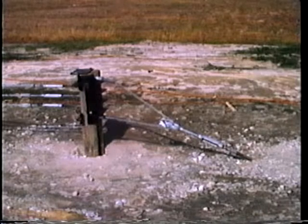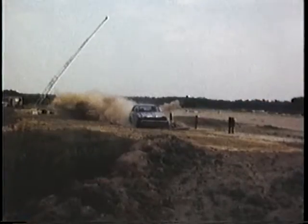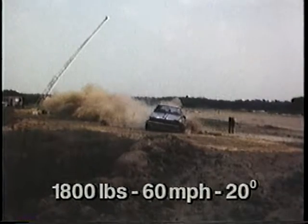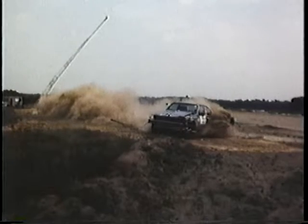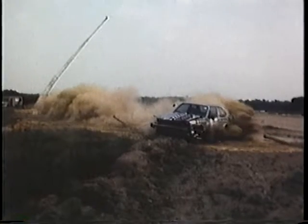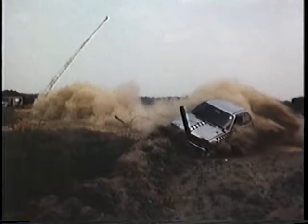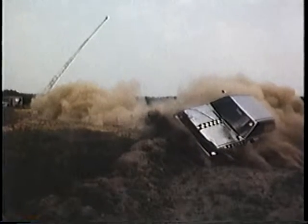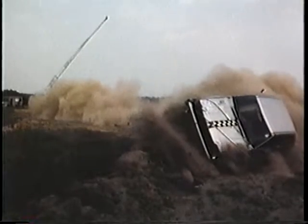As with all types of longitudinal barriers, designing effective end treatments for cable guardrails has been a difficult problem. Vehicles tend to stay in contact with cable guardrails longer than other barrier systems. This is generally desirable, but as posts are weakened to soften the impact, the cable anchor takes more and more of the impact load. If the anchor is too strong, it may not break away if a vehicle strikes it. When an impact occurs near the end of the guardrail, the vehicle can wedge under the sloping anchor cables, causing the vehicle to roll over.